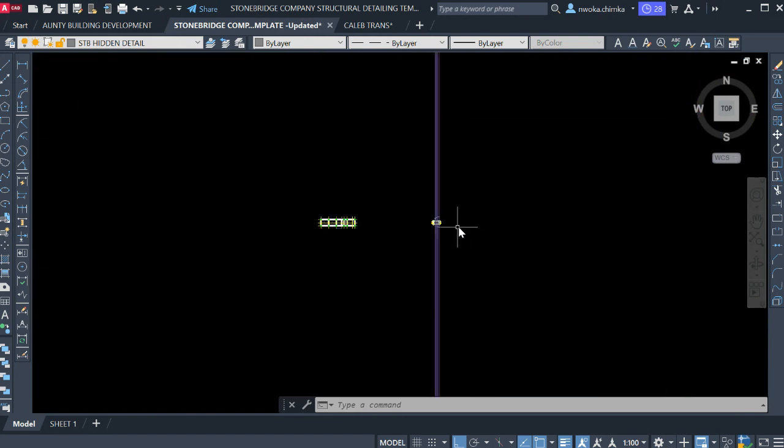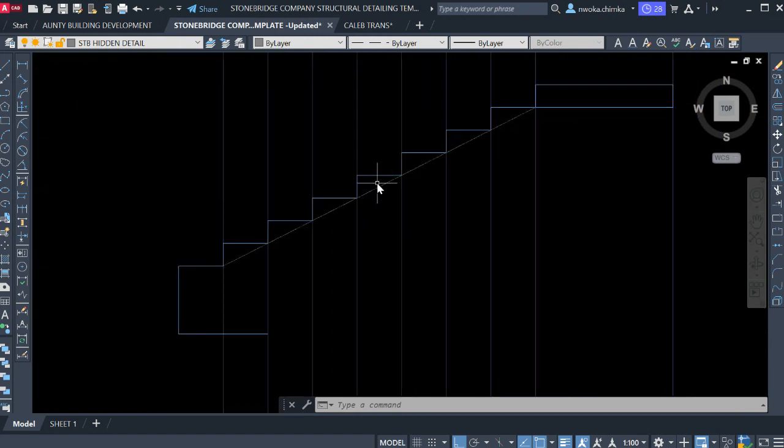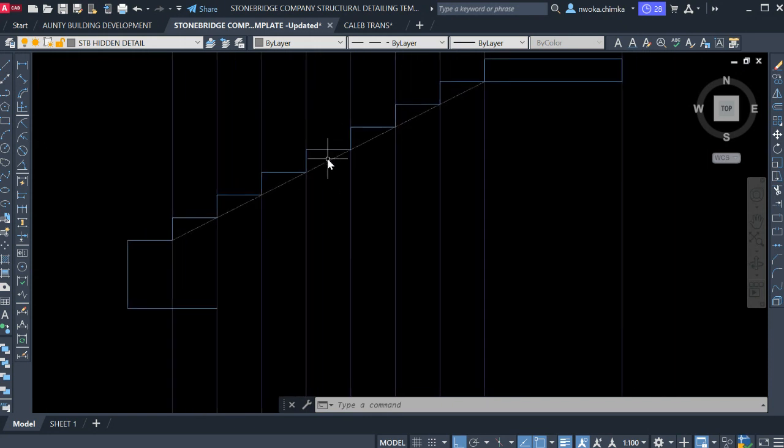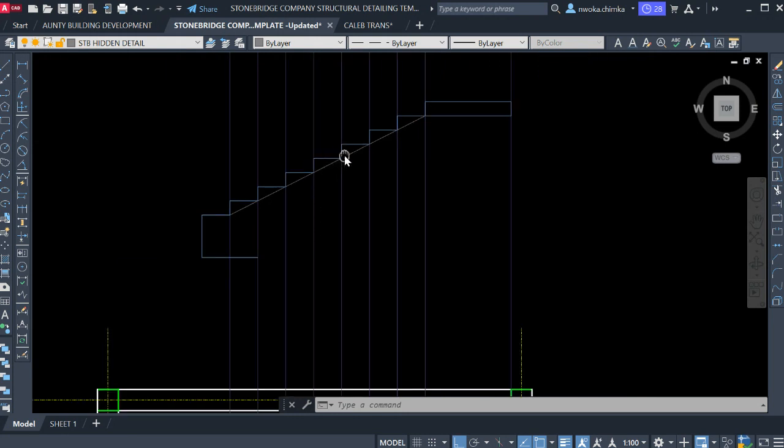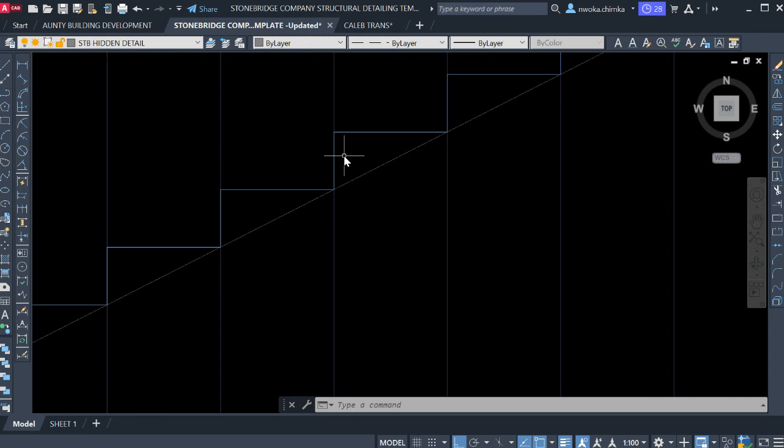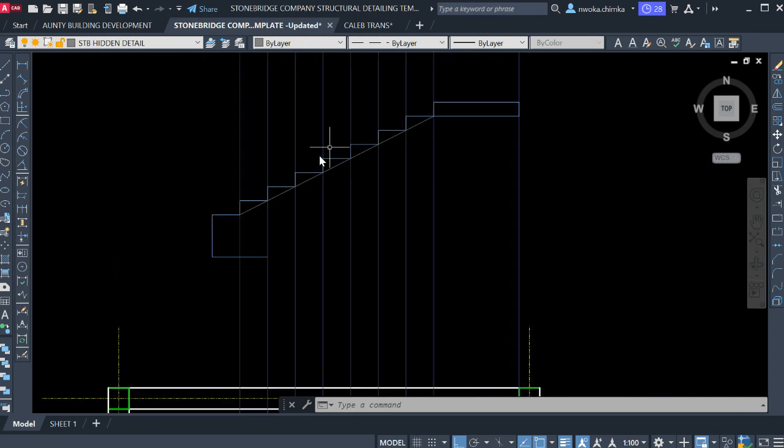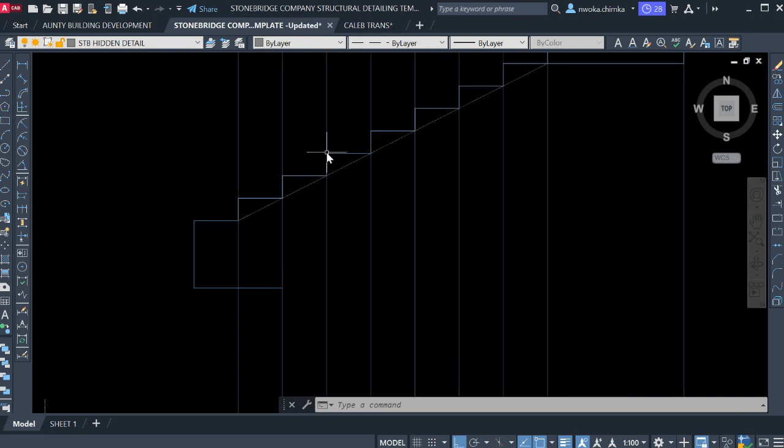A staircase waist is always, most people use 150, but I advise that you should use 175 at least, minimum 175. Most people go ahead with 150, but 150 becomes very tiny at this span of the staircase, and most times it tries to shear or break into two. So I'll say you should use 175. 175 is good for this staircase waist.